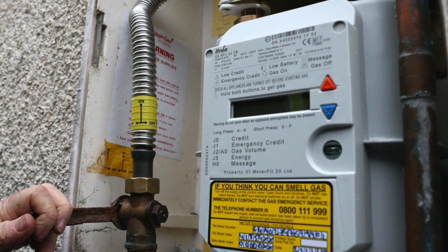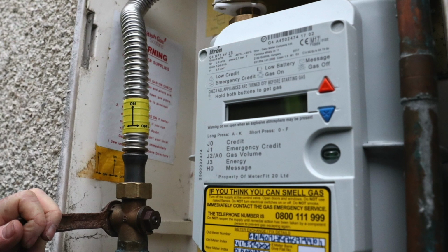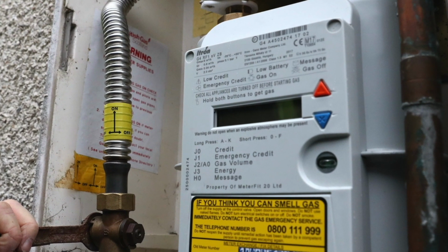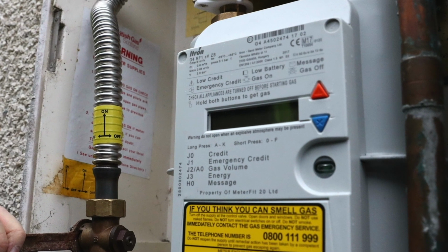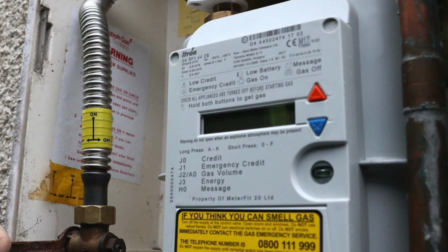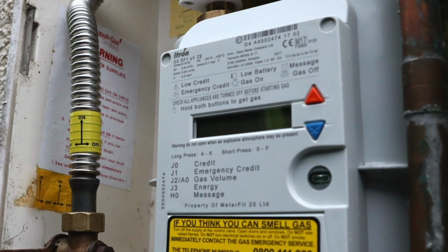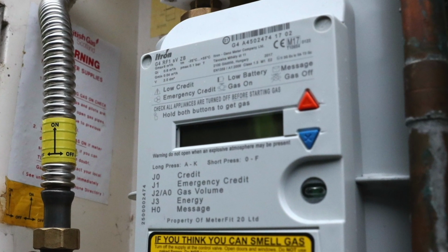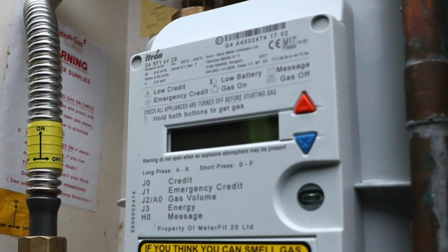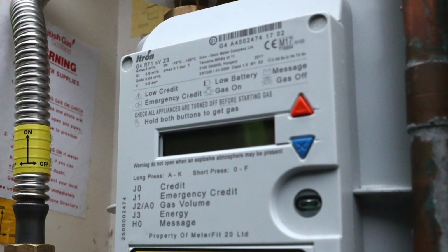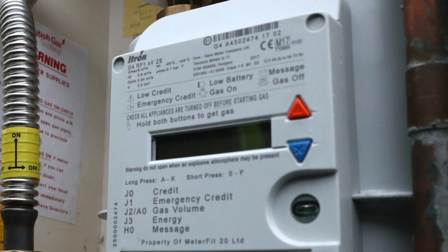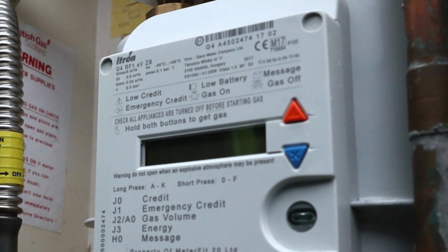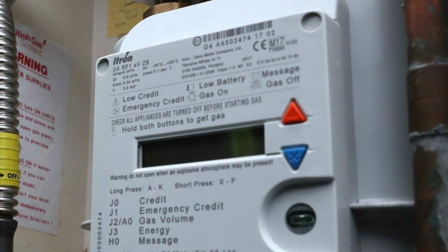But after 30 seconds the index will go blank, but the meter will still be measuring the flow taken during the test. So after 1 minute and 30 seconds we can press any of the blue buttons or the orange button again and it will reawaken the display. This will show the updated meter index, but we need to wait till we've met this 2 minutes or this 120 seconds before we take our second reading.